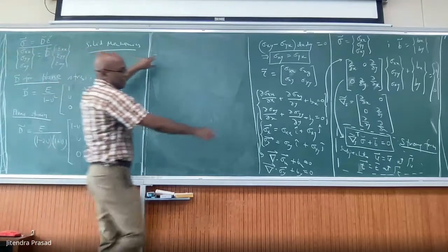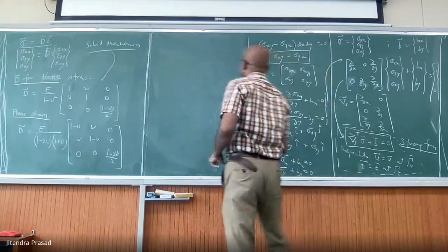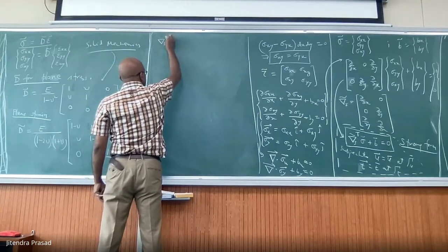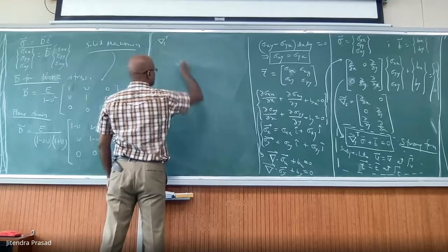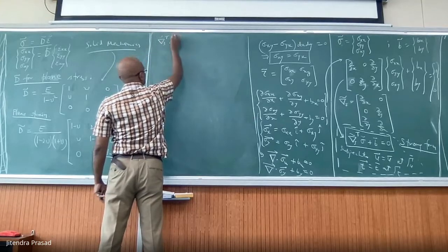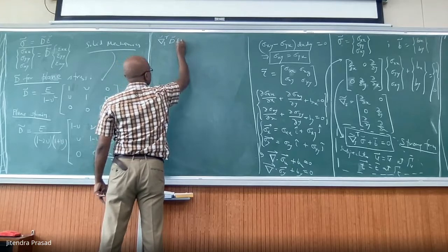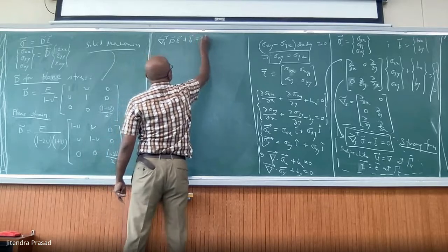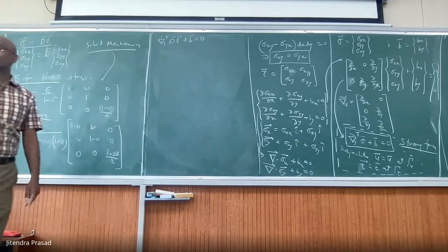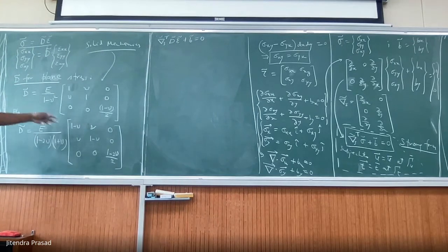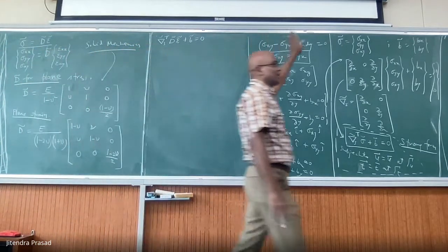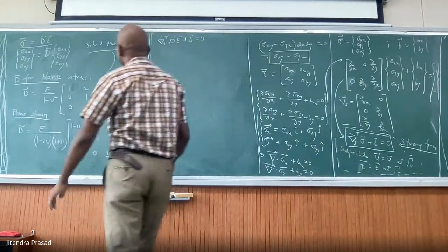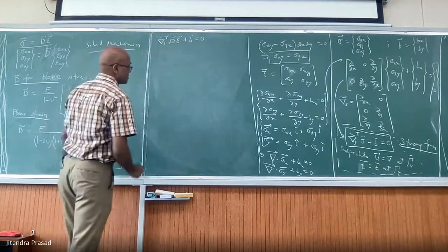So our equation you can write as the equation of equilibrium, this T, and then instead of sigma we write D epsilon, plus B is equal to 0. And now sigma is gone. We have epsilon, a strain there, and hence next thing is how we derive the strains basically.